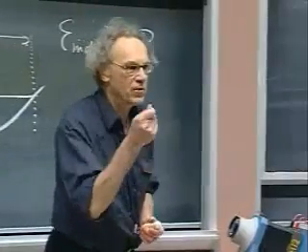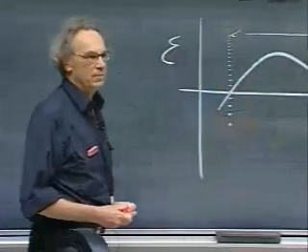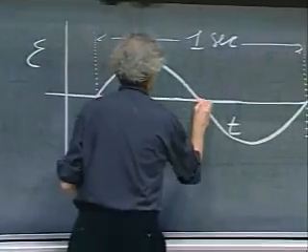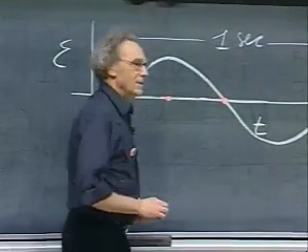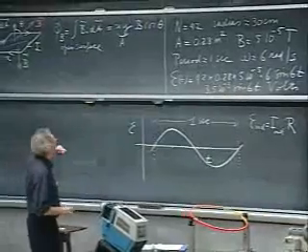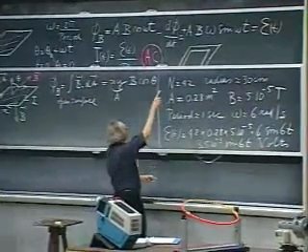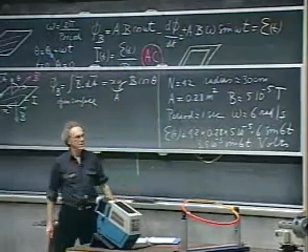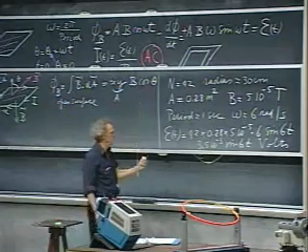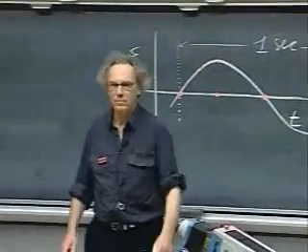Suppose now I rotate twice as fast. I double omega. Two things are changing now. For one thing, the full period now goes from here to here in only half a second. But there's something else that changes. The EMF now doubles, because look at my equation. It's hiding behind the blackboard, I think. There is an omega in there. It's linearly proportional to omega, because it's the dphi/dt that matters. So the omega pops out. And so you now get double the EMF. So the 3.5 millivolts maximum would become 7.